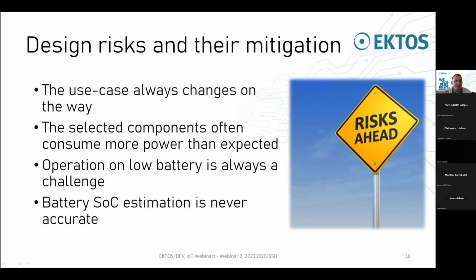Basically, the design risks are: the use cases always change on the way. The selected components often consume more power than expected. Operation on low battery is always a challenge, and a battery state of charge estimation is never accurate. So let's focus on each of them.